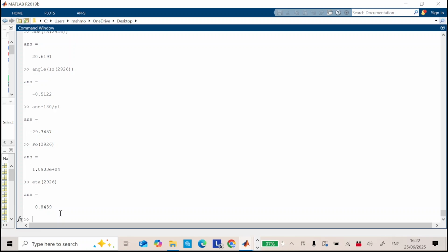What is the maximum value for the torque? What is the starting torque? So let's start with the starting torque. To have that at starting, NR at point number 1, so T of 1 represents the starting torque. So we have a starting torque for this machine of 68.64 Newton meter. Starting current, absolute value of I stator of 1. That one gives you the starting current 110.4 ampere. So you can do that at the point of starting.